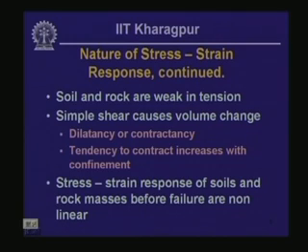And also you should have noticed that the shear strain response, or deviatoric stress versus axial strain response that we illustrated when we were talking about the triaxial tests in the last lesson, was highly nonlinear before failure, before reaching the peak value of the deviator stress. And in this particular case we are taking the peak value of the deviator stress as the condition for failure.